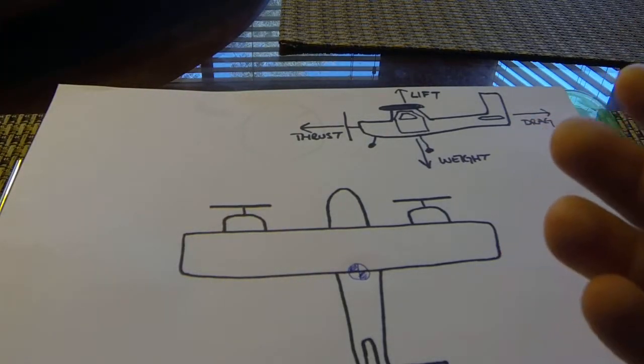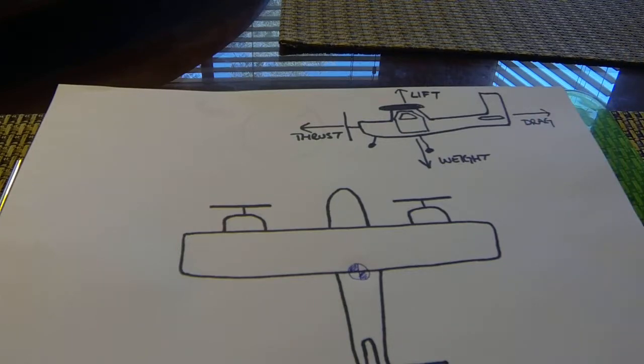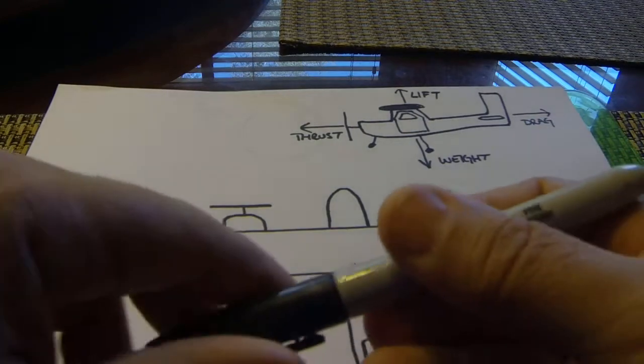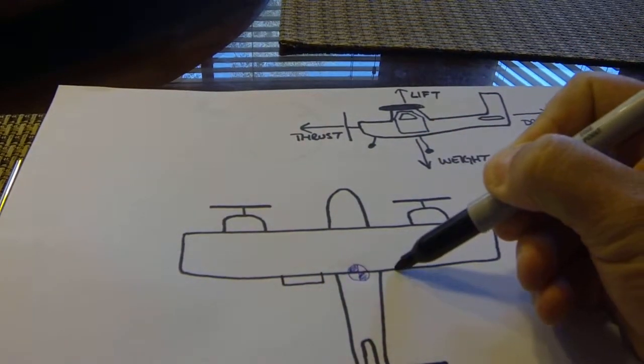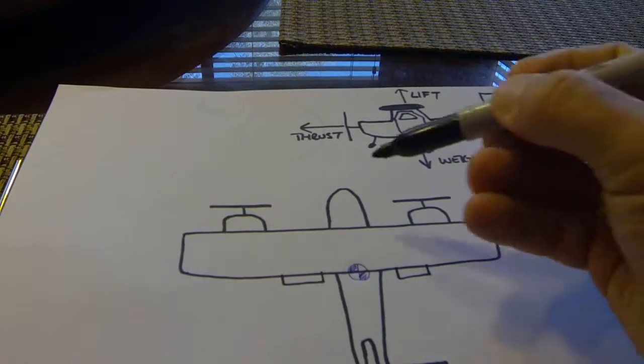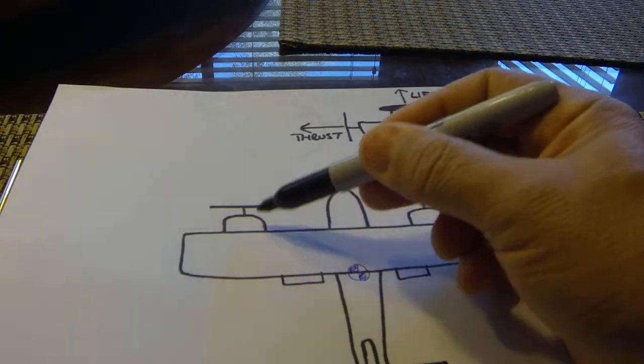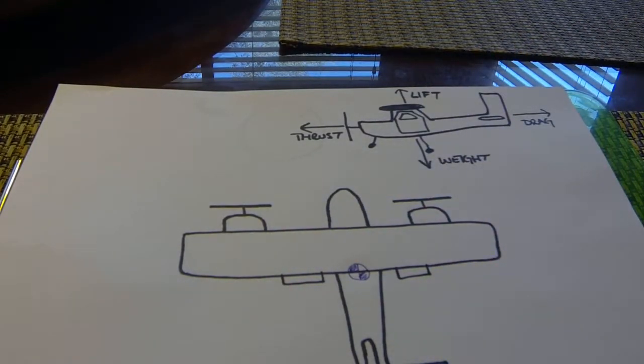Next, flaps. Flaps are in takeoff position, both wing flaps back here, as well as our cowl flaps on the engines themselves. So flaps, wing and cowl, in takeoff position. Landing gear, retracted.